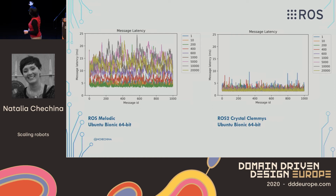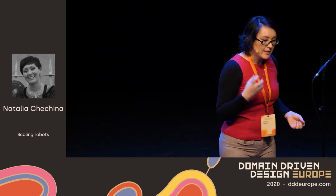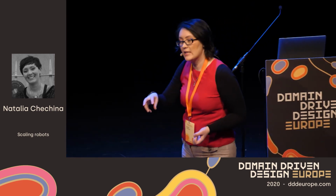If we look at ROS2, it usually stays between 2 and 5 milliseconds with different frequencies, whereas message latency in ROS is much more spread out. The difference is that in ROS2 they first of all removed the master node, with which you need to talk to register your nodes. The second thing is they changed the communication channel, so it was designed to handle more messages. When we talk about fault tolerance, ROS2 handles it better, in that if a connection or something else fails, it keeps working.